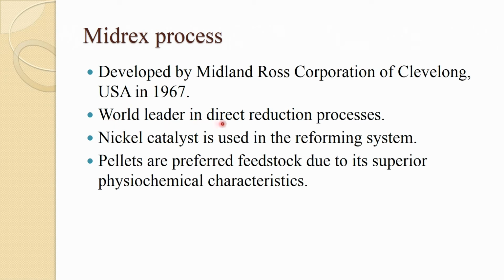It is a world leader in direct reduction processes. Nickel is used as a catalyst in the reforming system. Pellets are preferred feedstock due to their superior physicochemical characteristics, and even the properties can be controlled when you make the pellet instead of lump ore.